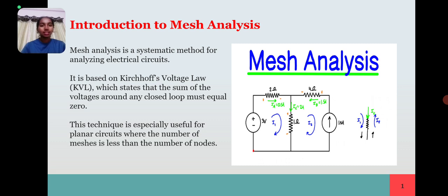Mesh analysis is a systematic method for analyzing electrical circuits. It is based on Kirchhoff's voltage law, that is KVL, which states that the sum of voltages around any closed loop must be equal to 0. This technique is especially useful for planar circuits where the number of meshes is less than the number of nodes. So here in the attached figure we can identify two meshes, that is mesh 1 and mesh 2.